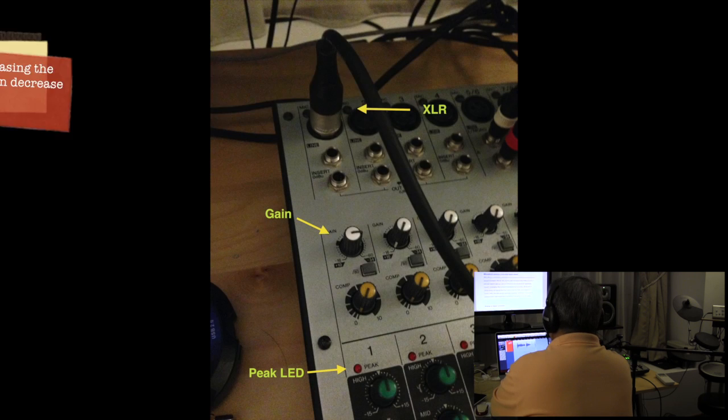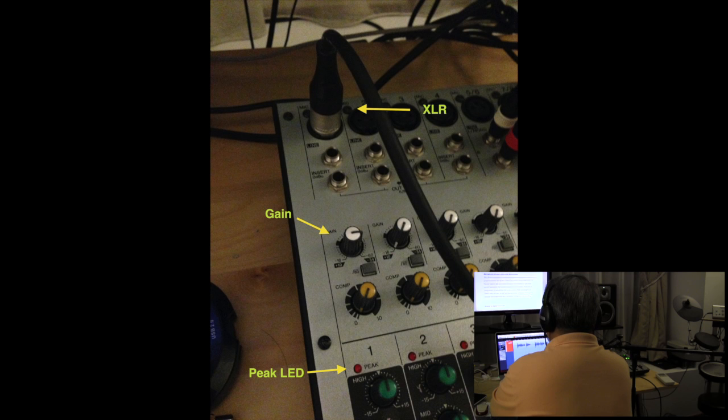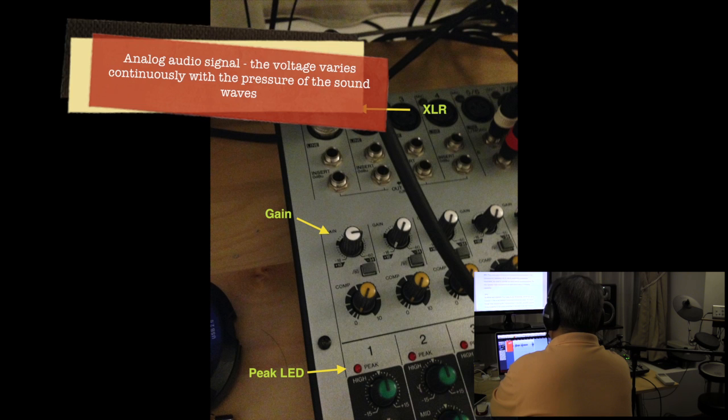Our audio interface is a Yamaha MW12CX mixing console. It's basically a mixer with a USB interface. Prior to recording, we need to set up the microphone so that it is in proper line level. We do this via the gain knob and the peak LED. The mixer also functions as an analog to digital converter.